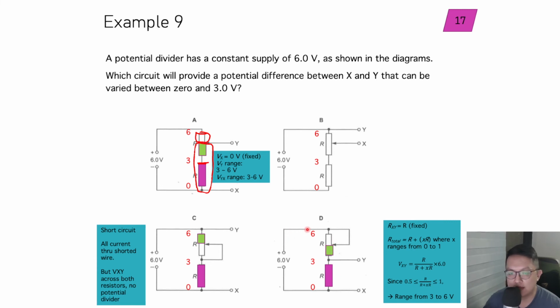So this slider here is allowing you to bypass the non-colored part of the resistor. So you can tap down to here. If I slide the slider all the way up to the top, it will use the entire resistance. So this portion here can be between 0% coverage or 100% coverage.